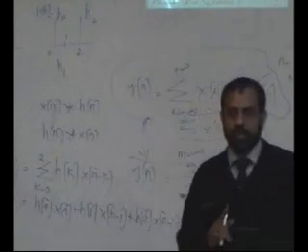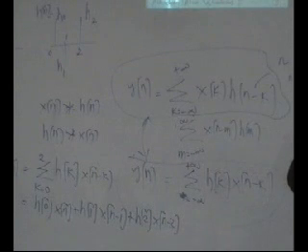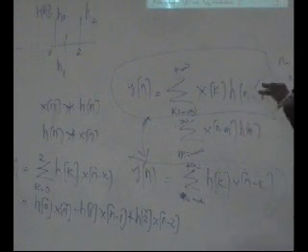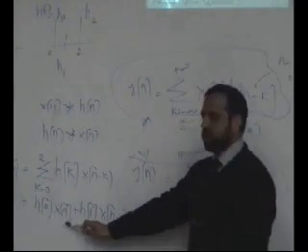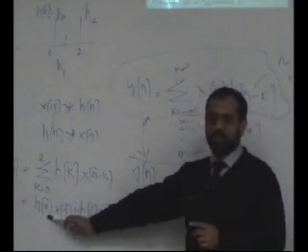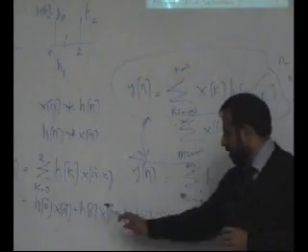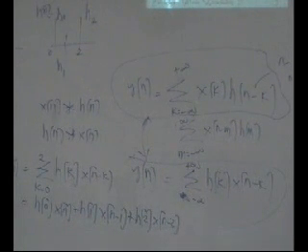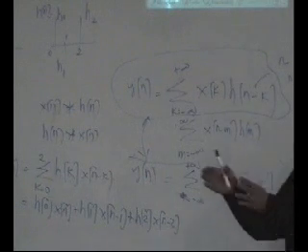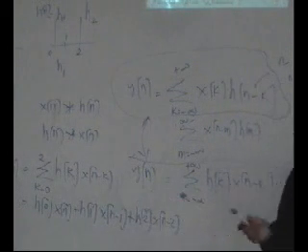So one way of computing convolution is that for every impulse you make an impulse response, then add all the impulse responses together, and you get an answer. That is not very trivial to code. This is very trivial to code: you acquire the current sample, multiply it with h0, you need to keep the previous sample and previous to previous sample. Multiply the previous sample with this number and previous to previous sample with this number, then you update your samples, because now the current sample will become the previous sample, and the previous will become the previous to previous sample. Just keep repeating this and you implement a system.